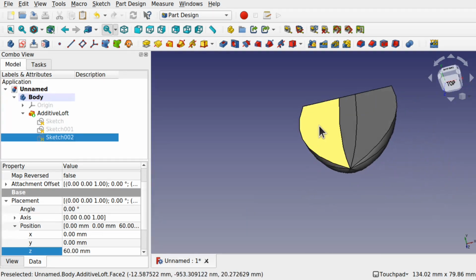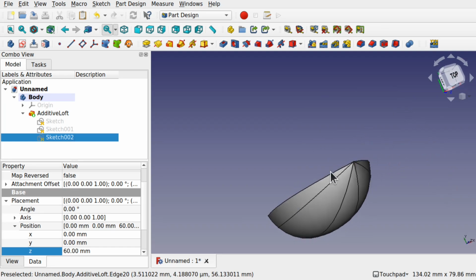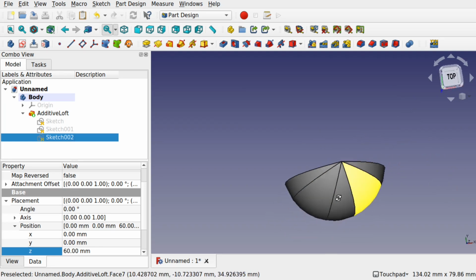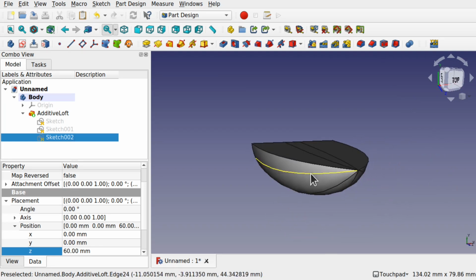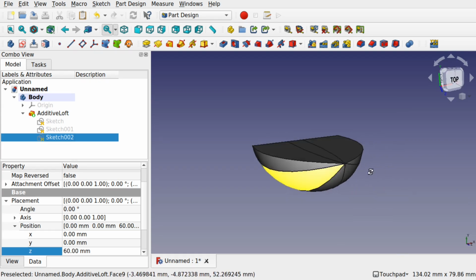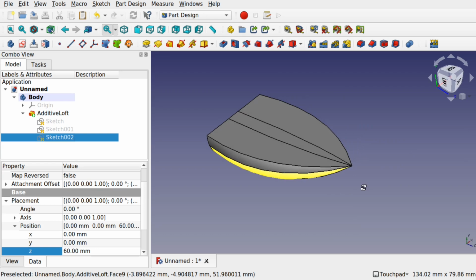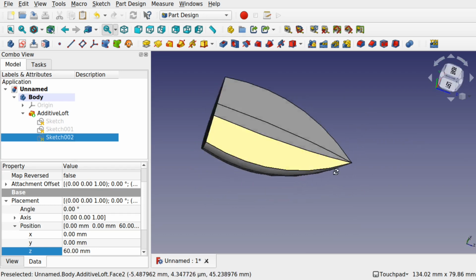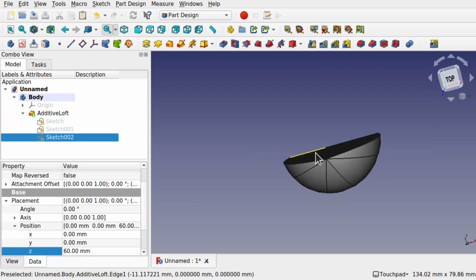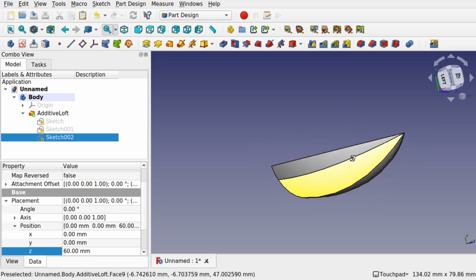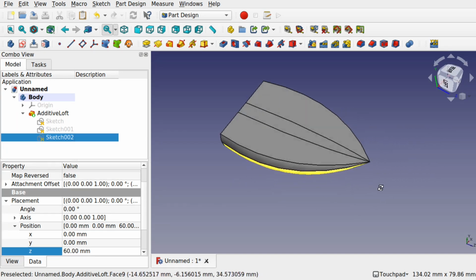We've got a nice even distribution of the faces along the bottom. So this face will be the same as this face because we use the horizontal constraint in there. This is pretty useful, as you can see, so we can actually section up the views like so.